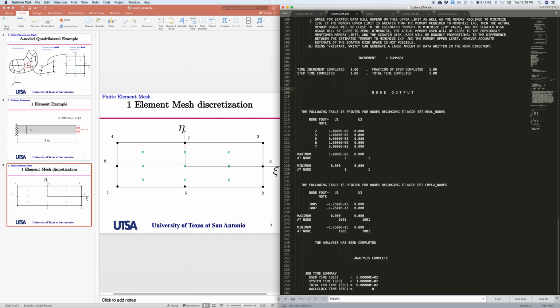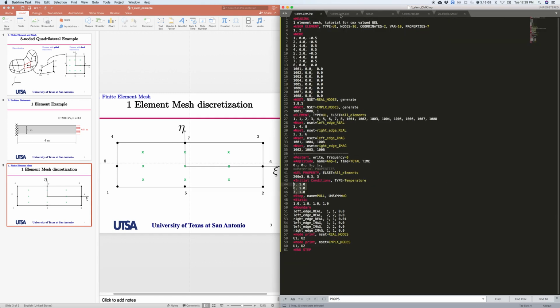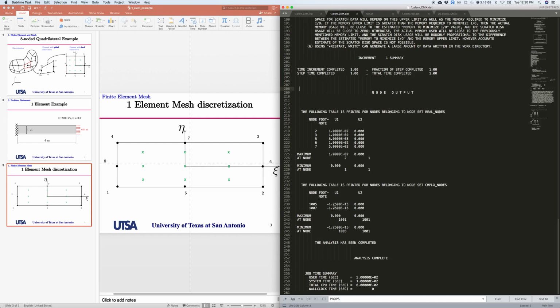Okay, so you do this. Remember the value of the perturbation is 1, and here you have to divide it by the perturbation step size, which was 1 to the negative 12. So that's only the delta coordinate of that. This is the derivative of the displacement in x with respect to a longer beam, the derivative of this node with respect to the length of the beam, because if we expand this part, we are making the beam longer.